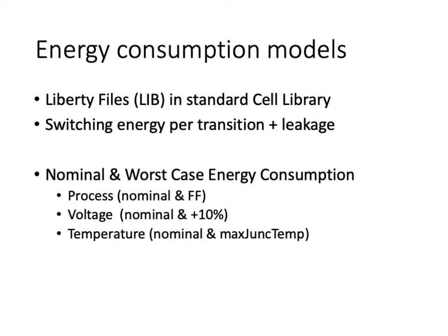And the description of this set of very specific transistor level logic gate designs is contained within a library file, and they are collectively referred to as the standard cell library. The standard cell library is a library of all possible logic gate implementations up to the transistor level that can be fabricated by a particular fab house. And the standard cell library is associated both with a fab house and with a particular process.